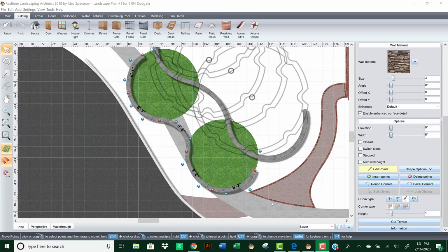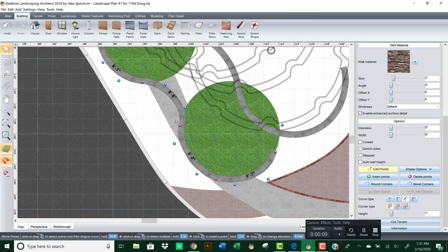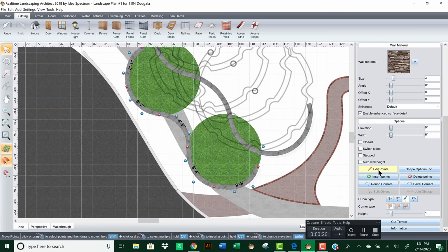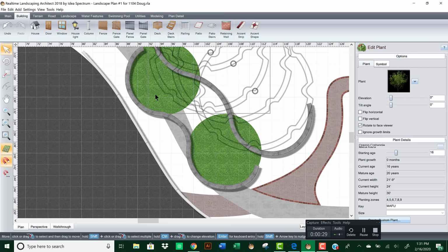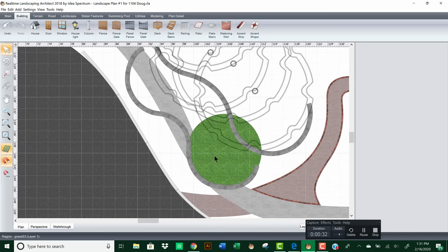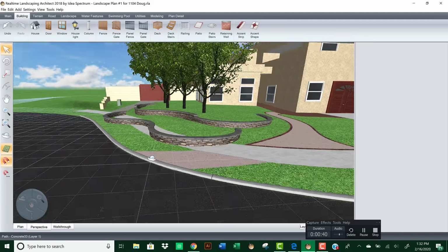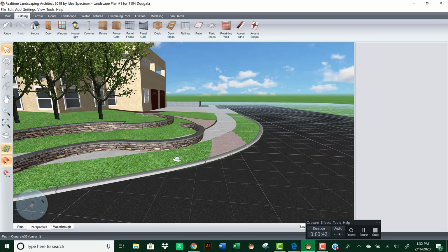Okay, so I'm going to zoom in here just a little bit more. And you can see this angle's a little off. We can correct that a little bit. Still a little bit off. So this one will have to pull a little more. And that's a pretty good angled wall right there. So I'm going to unedit these, select this, delete, select this, delete. Go back into perspective view, and we can click the right finger on the mouse to allow us to pan through like this.